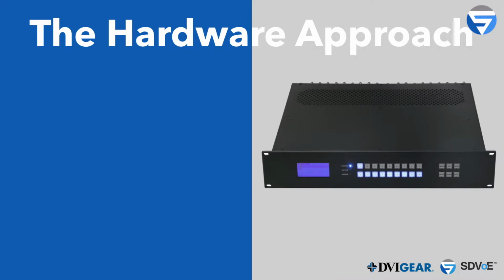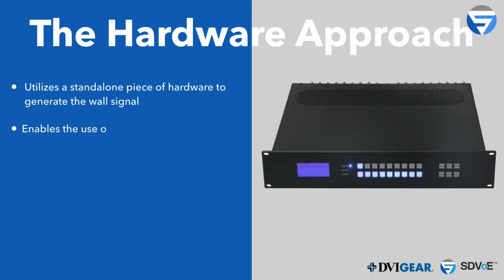There are three approaches to installing a video wall. There's the hardware approach, where you have a standalone piece of hardware to generate the wall signal, like a video wall processor. And there are some advantages, pros and cons to each approach. The hardware wall processor enables the use of any HDMI source because it is a hardware-based video processor. It has very good synchronization performance because it's pulling the frame from the source and distributing it all internally.